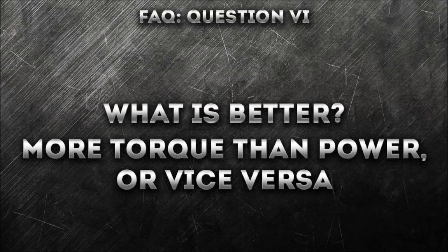Question number 6. What's better, more power than torque or vice versa? The question itself makes as much sense as, is it better to have more orange juice than oranges or vice versa? Power and torque do not have the same units, so you cannot compare them, but neither can you really separate them either. Let us form a question out of this, which actually can be answered. What shape of power curve is preferable?